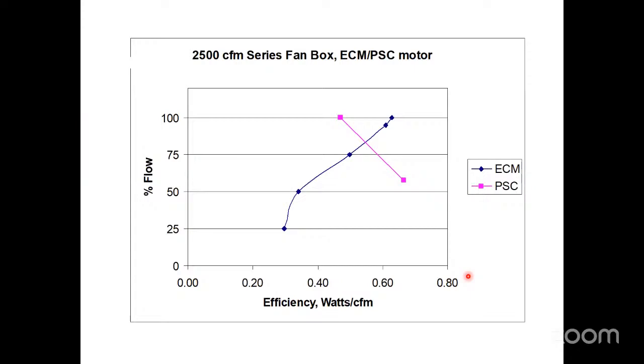Sometimes, so in general, PSC motors are less efficient than ECM motors. You're probably aware since 2019 on furnaces, PSC motors are prohibited. You cannot install a furnace with a PSC motor. Actually, you can install one. They can't manufacture one anymore. So we're 7 years into that.